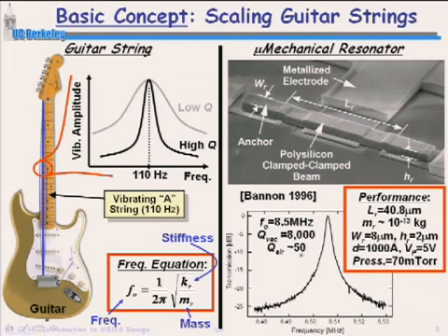For inductors, the problem is that the energy is proportional to omega, the frequency, times the inductance. So the reactance gives you what the energy is. You have to divide that by the losses, which are determined by the resistance in the system. An inductor is a long spiral of conductor. That's a lot of resistance in the end. And the omega L that you can generate is not that much bigger than the R that you have. So that's just electrical. In an electrical system, that's what you have.